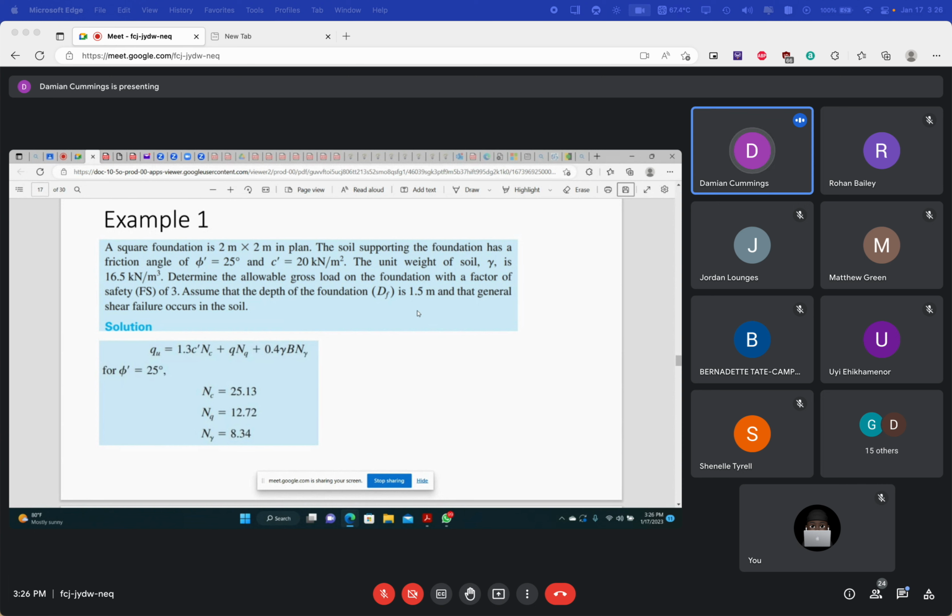The factor of safety, you are going to determine that as well, that you are going to use, or from the code that you are using. Also, the friction angle, the soil's cohesion, and the unit weight of the soil, you will get that from the soil study. So the geotechnical engineers, your company like Gentech or so, do the investigation, and they would give you those values for the soil that you're working with.